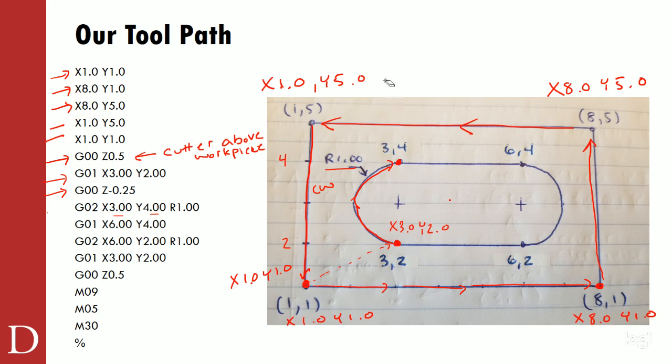All right. So what you'll see on that next item there is that what I did was I took a clockwise cut from 3.2, which was right here, and I did a radius of 1 up to 3.4, which is right here, which will take me right along that edge precisely the way I want to do it. And I noticed in my print it did actually give me radius 1, so I actually knew what that radius was. Next I'm going to go over to 6.4. So I've got my cutter in the part still.